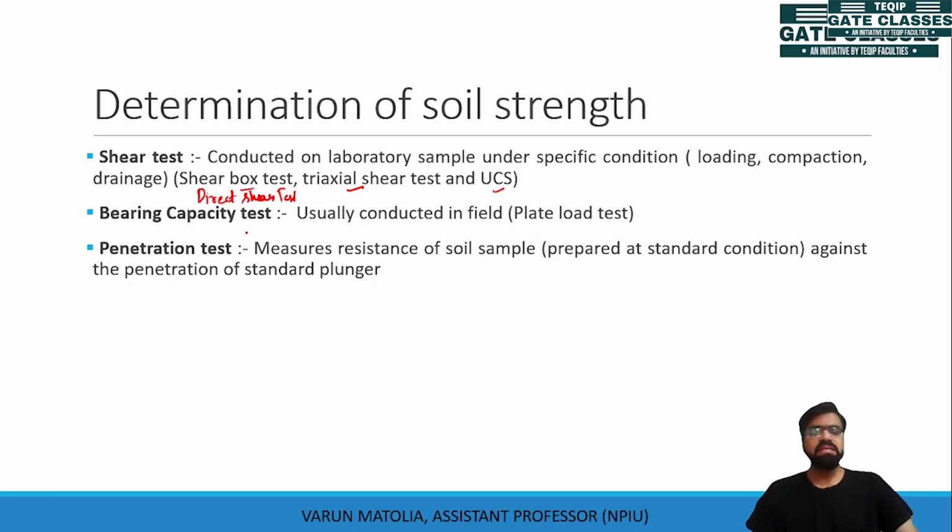Bearing capacity test is a field test which is known as plate load test, which is a very important test for your highways, because we need to know whether the soil present can bear the coming loads. If the soil is not able to bear the coming loads, we have to add some additives and stabilize the soil to make it capable of taking external loads.